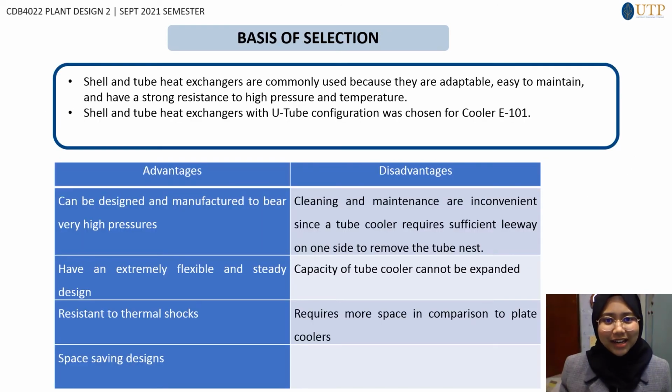A U-tube heat exchanger is used mostly according to the counterflow principle. For heat transport according to the counterflow principle, hot and cold medium flow in opposing directions. As a result, heat recovery of almost 100% is achieved. Counterflow heat exchangers therefore have a very high efficiency level.